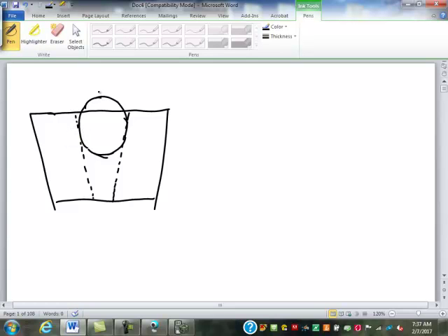So pretend that's not a horrible drawing of it. We have the width of the top of this opening here, given as 1.231 inches. I'm going to leave the inch marks off just for clarity right now. And this ball has a diameter of 1.2 inches. This is a number 4 Morse taper.